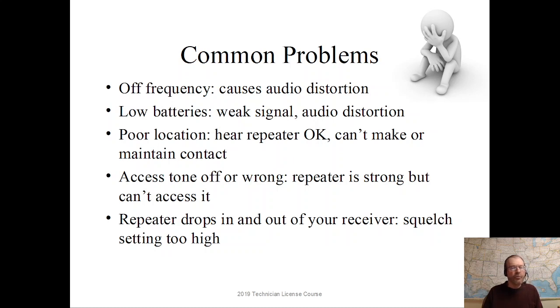And the repeater might drop in and out of your receiver, so there's the squelch setting on your radio, which again is an adjustment you might have to go to the instruction book for these days, but they are all preset, but you might need to set that squelch if you run into that kind of a problem.